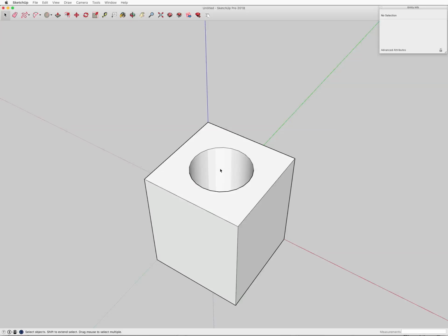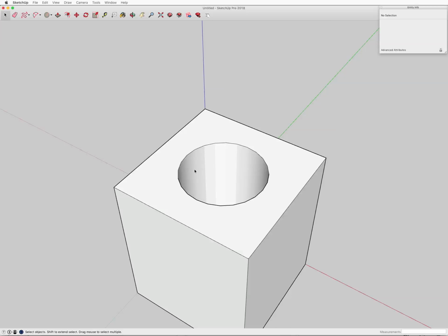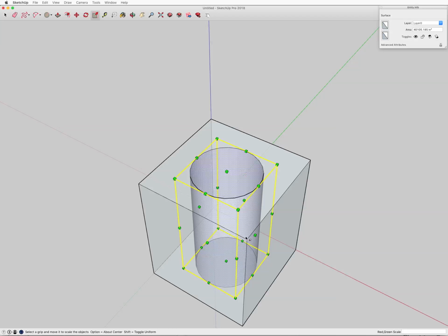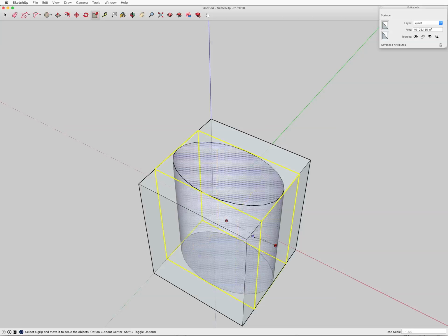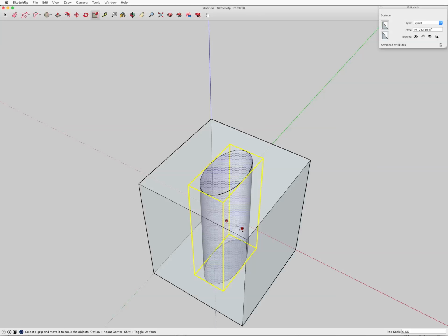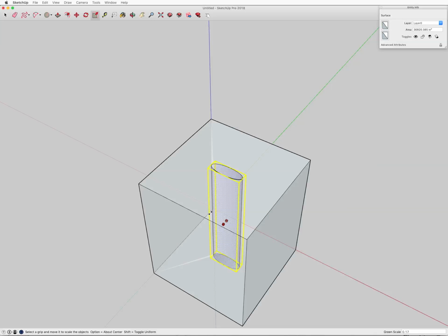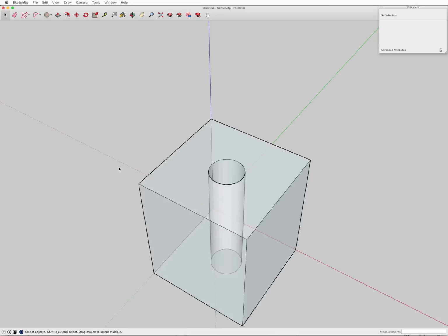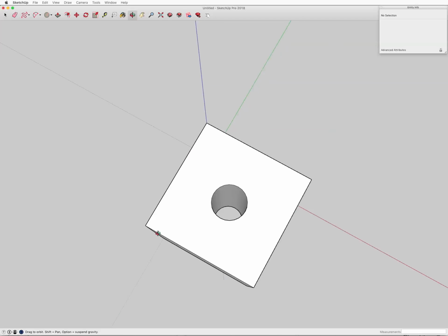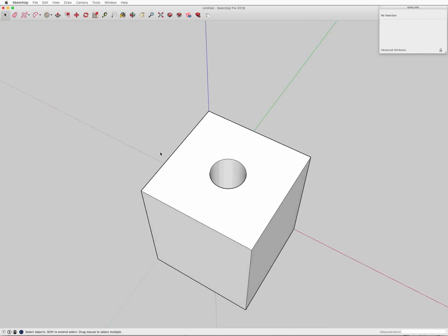Let's also examine what it would take to resize this cylinder here. If I select it, I can scale it, and I'll go into X-ray mode. And then I can scale that about the center. And you can actually scale things non-uniformly in SketchUp, which isn't possible in Shapr3D. I'm going to scale that to 0.5 also, so it's half as big. I'll go out of X-ray mode. So now the cylinder is smaller.